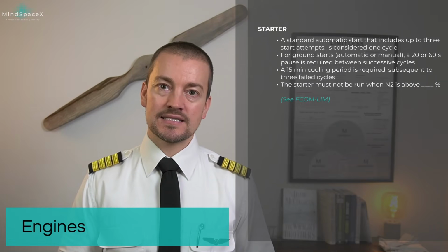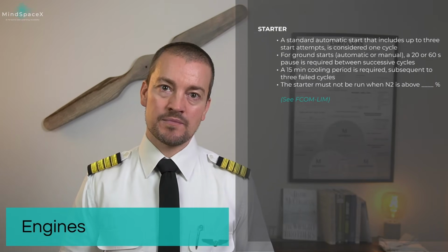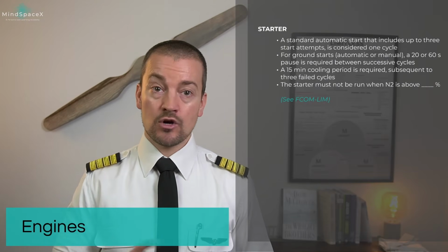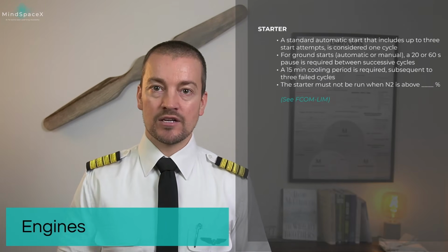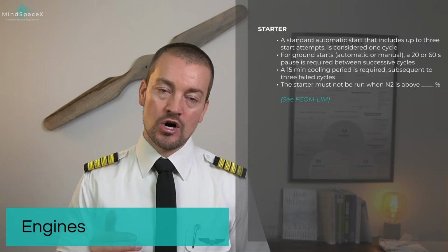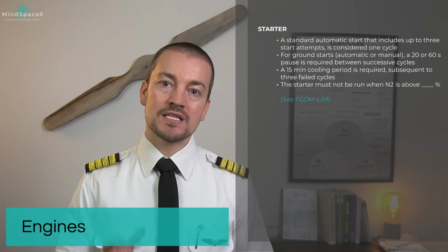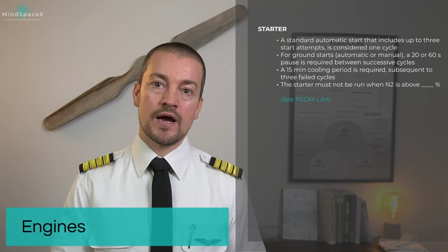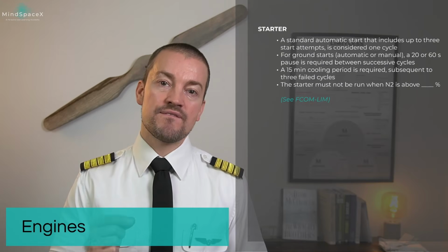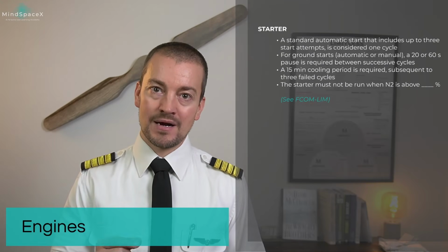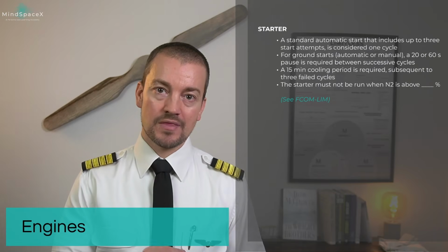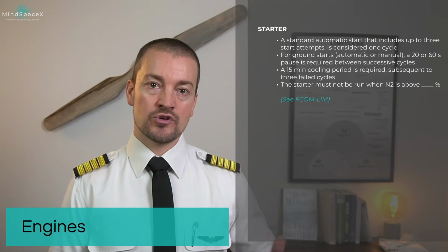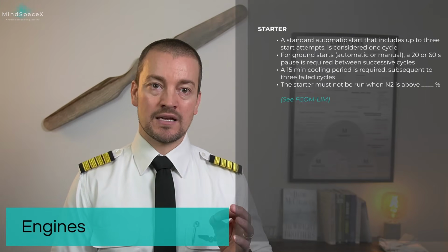A standard automatic start that includes up to 3 start attempts by the FADEC is considered 1 cycle. For ground starts, automatic or manual, a 20-second or in some cases 60-second pause is required between successful cycles. A 15-minute cooling period is required subsequent to 3 failed cycles. Remember, each cycle includes 3 attempts. The starter must not be engaged when N2 is above a certain value, and that is for your individual airplane engine.